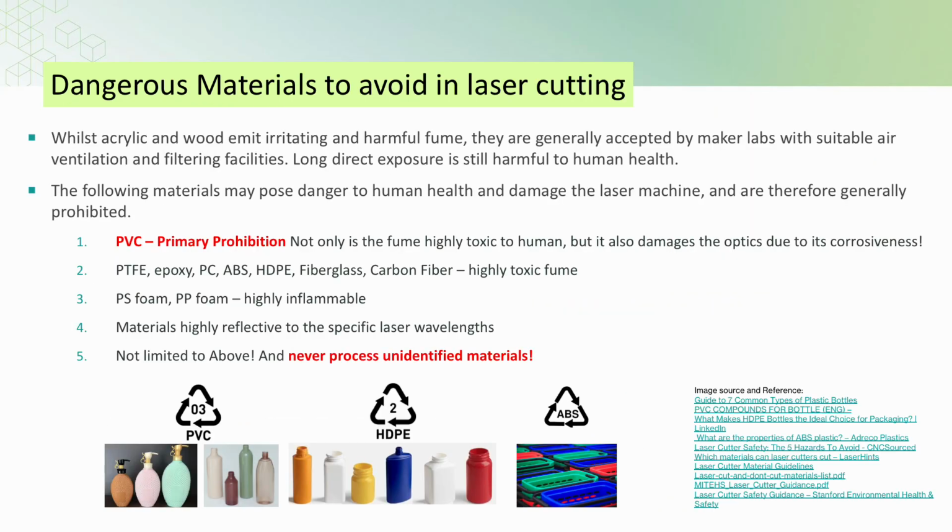About the hazards that come from material interaction with the laser. Acrylic and wood would emit irritating and harmful fume, but this is generally accepted by maker labs with suitable air ventilation and filtering. However, direct and long-time exposure is still harmful to human health. Some materials which may pose danger to human health and damage to the laser machine are generally prohibited.